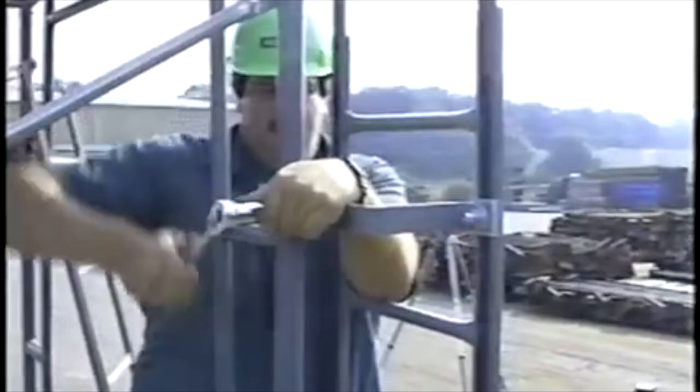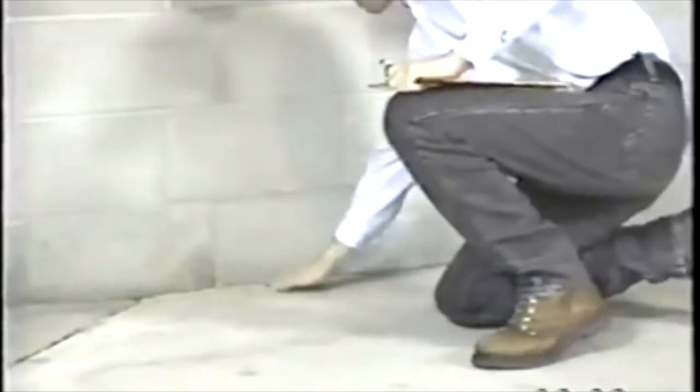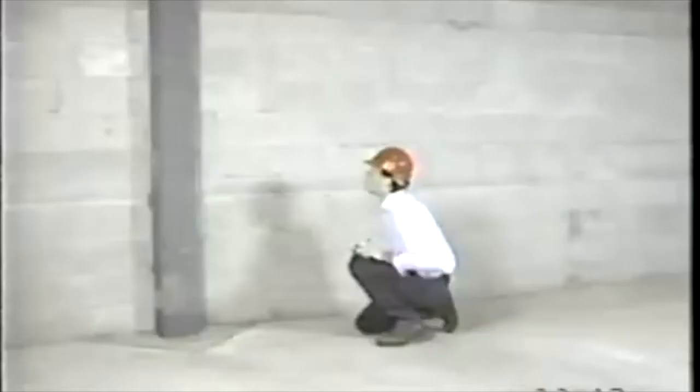To ensure further stability and reduce the possibility of tipping, the height must not exceed 4 times the least base dimension. For safe access, ladders or stairs must be provided, either built in or attached to the scaffold. Mobile scaffolds are limited in height to a single unit or section unless the entire system is approved in writing by a registered professional engineer, or it is erected in accordance with instructions furnished by the manufacturer.